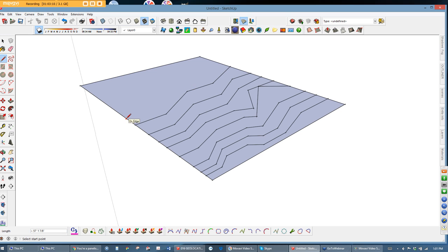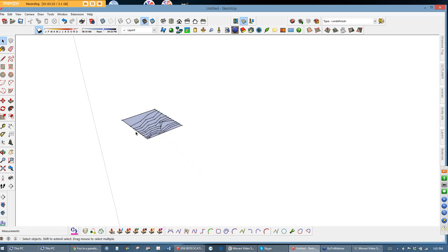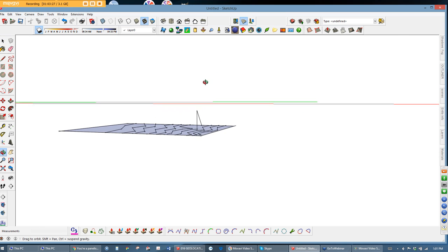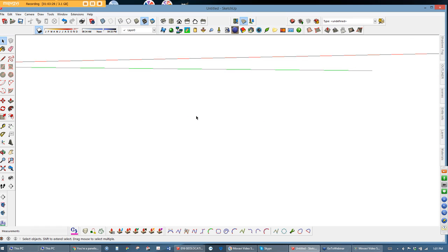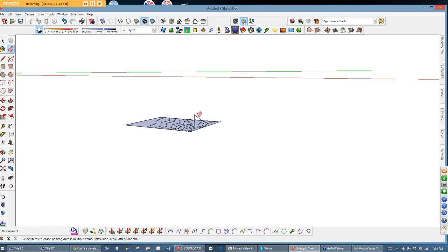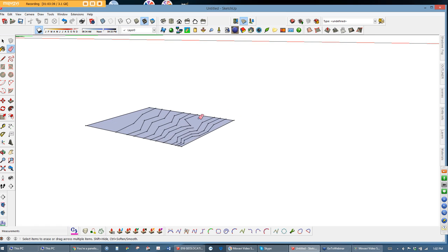These are cutting faces, so make sure when you're drawing this it says on face or from point. One of those options shows up. Okay, let's call that good. That's my topography. I've cut it into a face. Oop, there's one that went on the blue axis. Let's fix that. That's a no-no. Don't do that. So we'll redraw that.